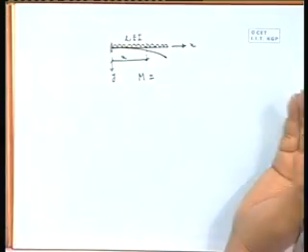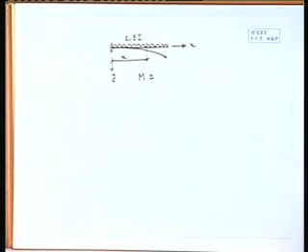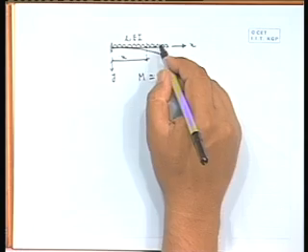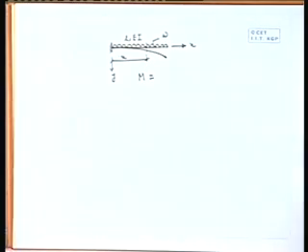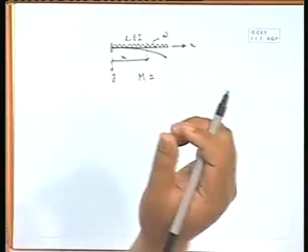Beyond that section on the right side, the length will be L minus x, and the loading is w or omega, that is the intensity of the distributed load, the load per unit length. So, total load will be w into L minus x, and that is in a distributed manner.